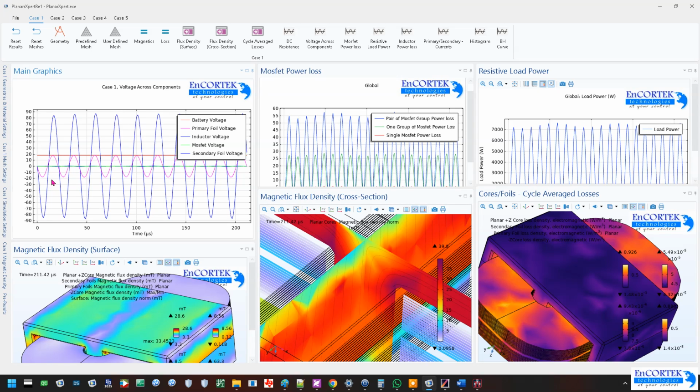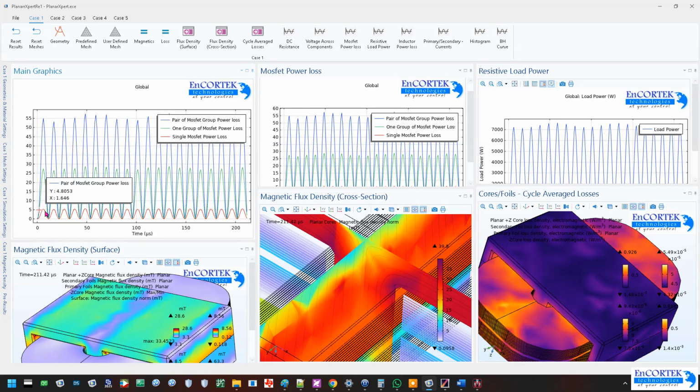So that is fine. Let us look at the MOSFET. We had a MOSFET over here, but I'm just pulling it up in the main window here. The main window is to browse through all. So the maximum power loss and heat is 57 watts. This basically means your heatsink could be very small. You don't have to worry much about heat, fans, and fins. You really could go compact accordingly. So this is really low losses in heat.